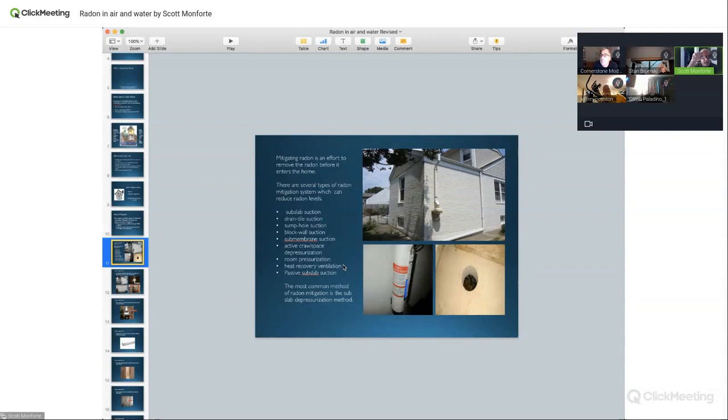If somebody loosens it, or over time it loosens or was never tightened up, now radon, instead of being drawn from the attic up, sucking up, you're blowing it all over the place. That's why they want it in an unconditioned attic. Because if you put a hole in the pipe, you're not blowing radon within the wall cavity. You're just sucking everything up.